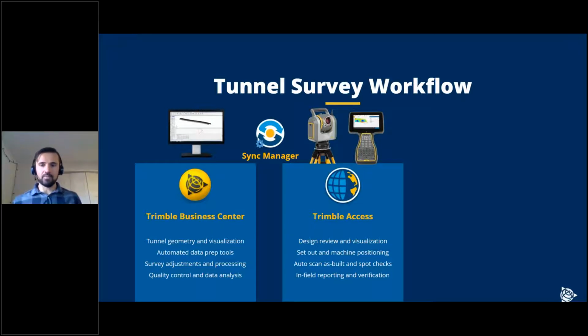So that same design information, same data in TBC transfer seamlessly out to Trimble Access. So when I'm in the field on the data collector, I'm seeing the exact same design, same alignment, same shapes, all of that information in Trimble Access. And I have access while in the field to tools to do any design review or editing as needed. If there's a change and I need to make it that second in the field so I can keep up with the construction crew, I can do it.